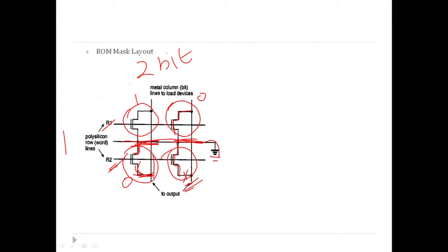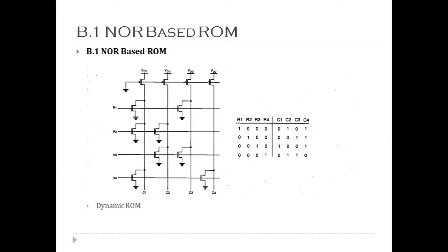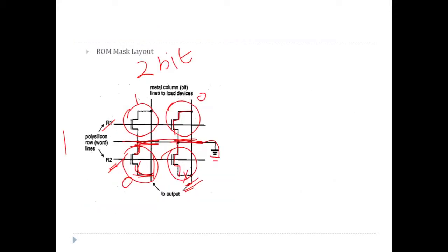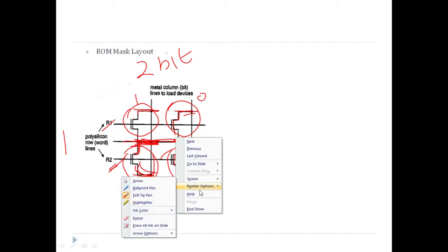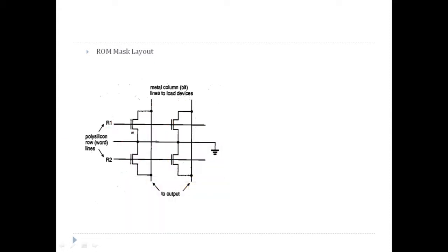It is a dotted connection, whereas source is connected to ground, the upper terminal. So what is the difference between these two things? Here you can see for R1, drains are the upper terminal and sources are the lower terminal. Whereas for R2, sources are the upper terminal and the drains are the lower terminal. So we can say R2 is drawn upside down, right? So basically it is storing 1 0 1 0 here, because there is no connection. While fabricating it, we can fabricate it, but while making the connection, we will not make the connection, that is a buried connection, metal layer contact.